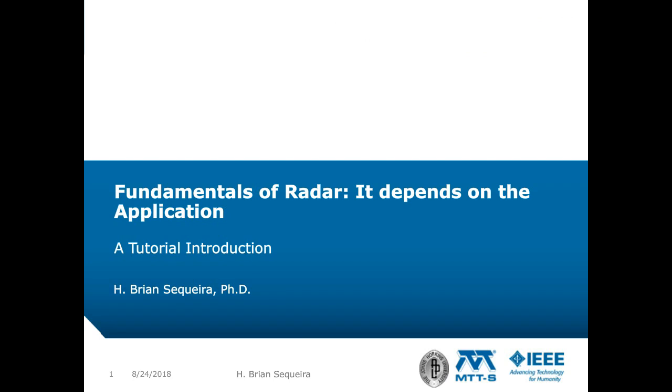The word radar is an acronym for radio detection and ranging. Its function is to broadcast a signal and listen for echoes of that signal. Encapsulated in this simple statement is a notion that a radar must distinguish echoes from other interfering signals in ever-present noise, and, having confirmed the receipt of an echo, the radar must measure the time lapse between transmission of the signal and its receipt, as the animation illustrates.